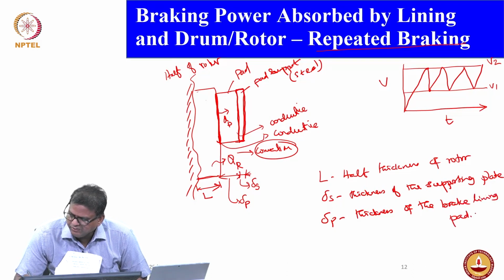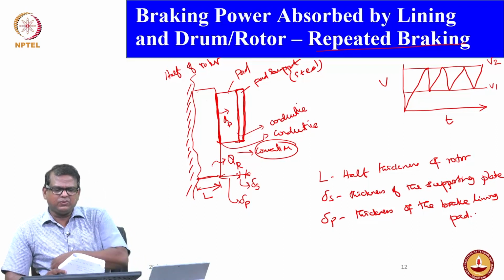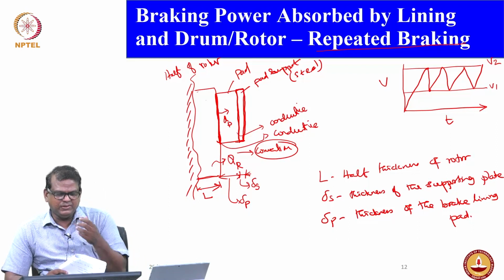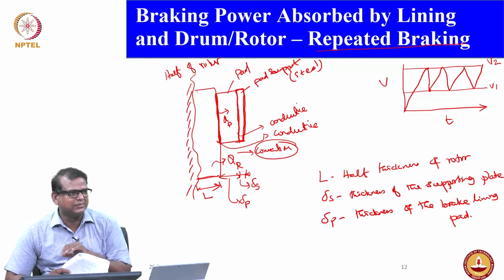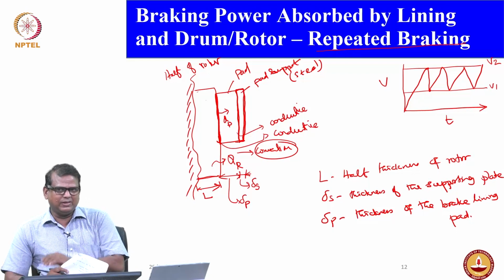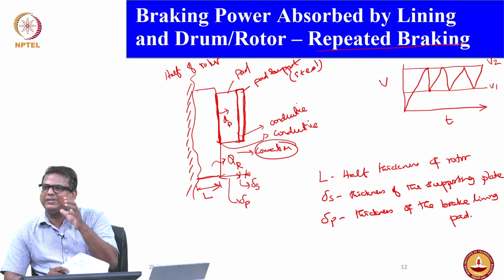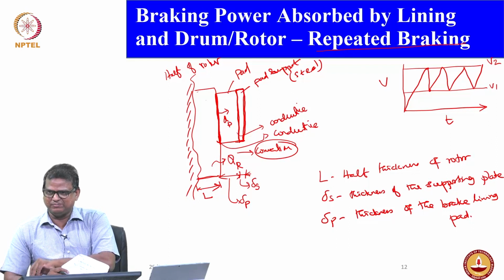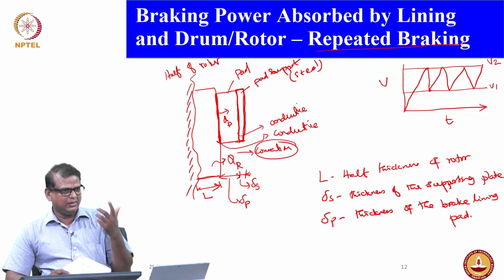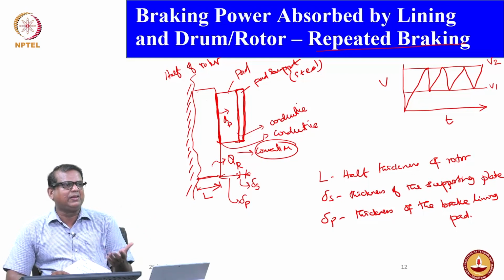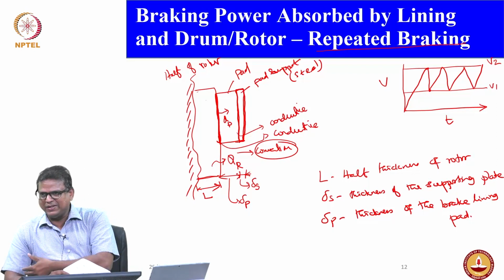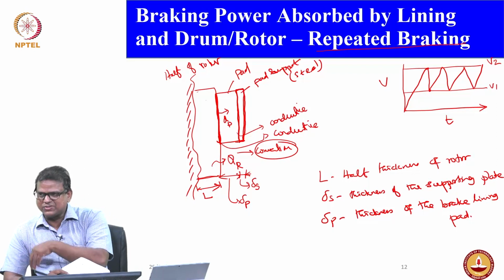Okay. We may ask the question, why are we so concerned about the thickness? As I said earlier, we need to identify the sizing of the brake system. So far we did the structural aspect, but as you are aware, the thermal stresses are very high compared to the mechanical or structural stresses.